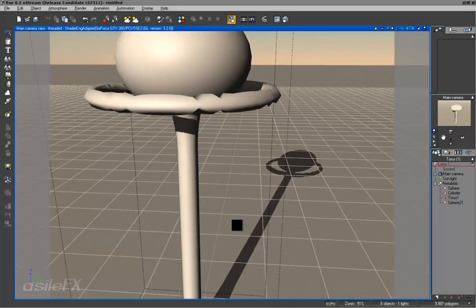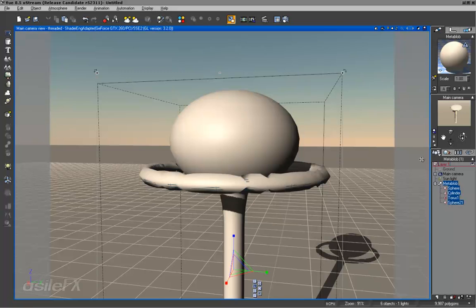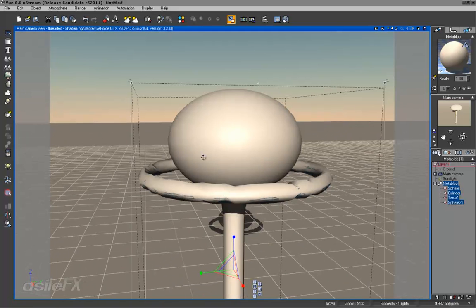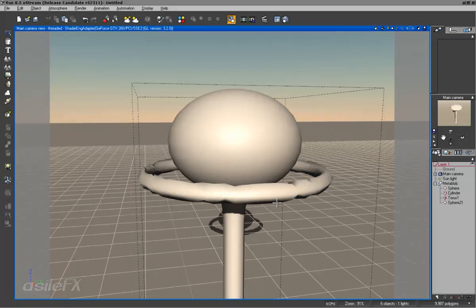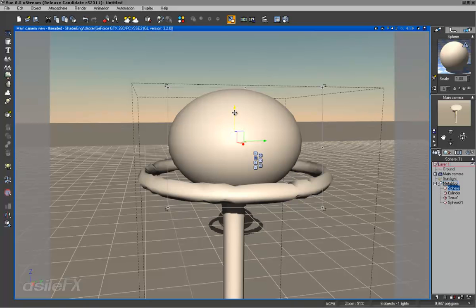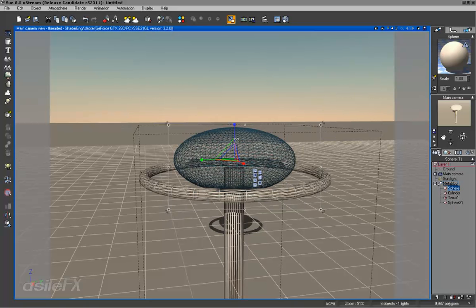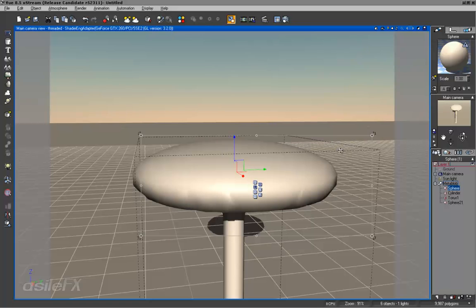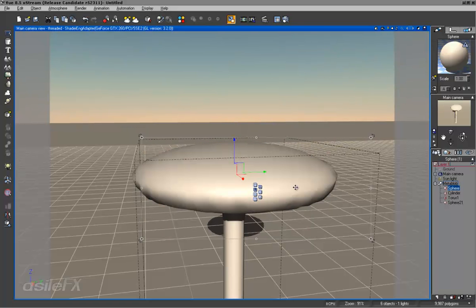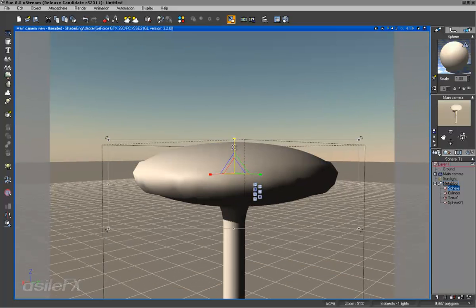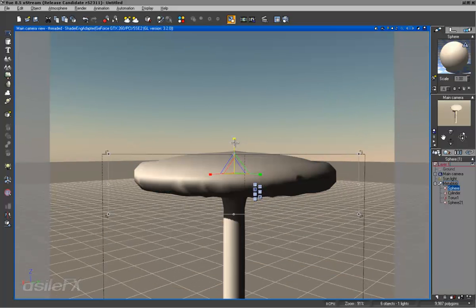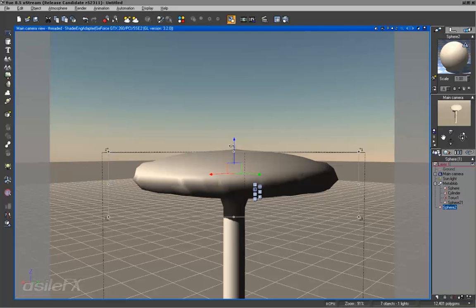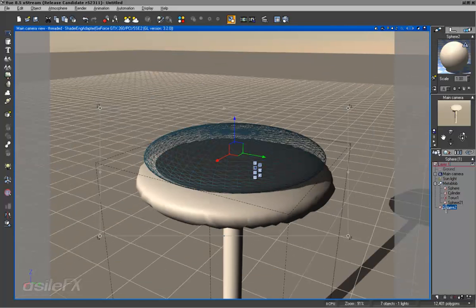If we go ahead and just remove the torus completely, we'll be able to see an edge and kind of that missing area. So we do want something that's going to build up a little bit better. So I am going to reposition our sphere. And hopefully we can just step this up a little bit higher. Right now that's a little too flat. And go ahead and copy and paste. Move up the duplicate. Add that into the Metablob.